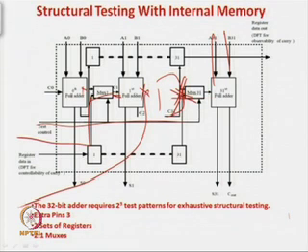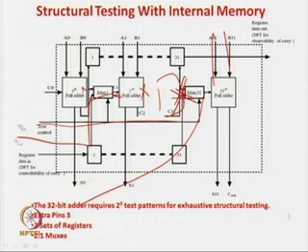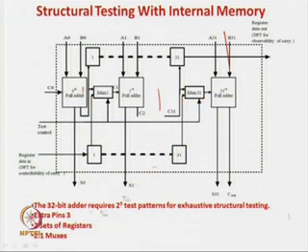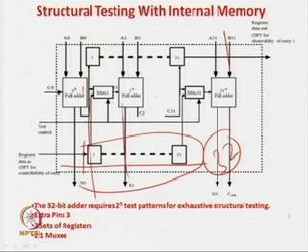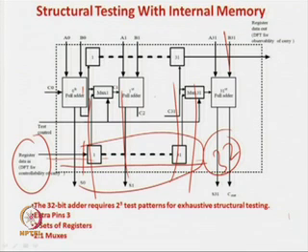Now, in the last example, to control this, we directly brought this out as a pin out, which was actually taking a huge amount of area, a huge number of pin outs. So, to solve the problem, they have put a shift register over here. Whatever carry values you require, you can shift into the shift register slowly. That will take 32 clock pulses, because now you cannot feed everything directly, you have to do it slowly, but now only one more pin out is required.